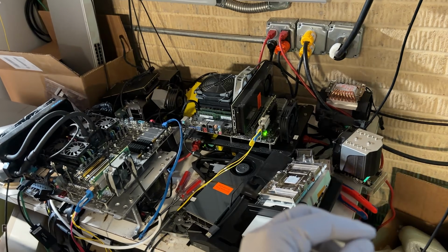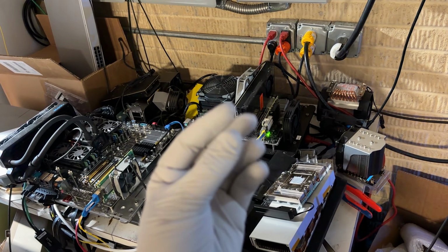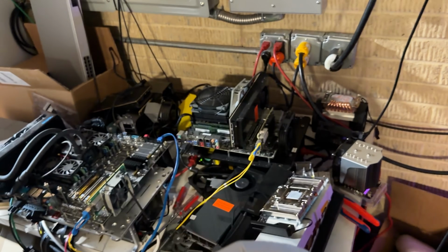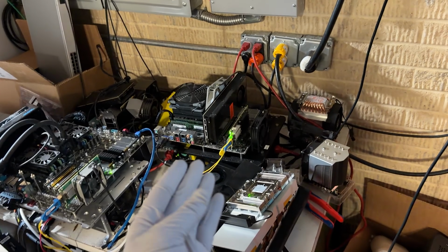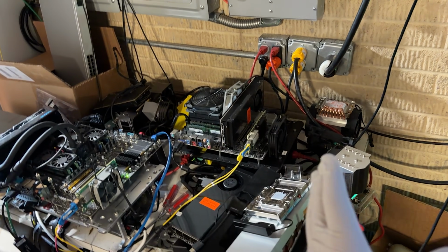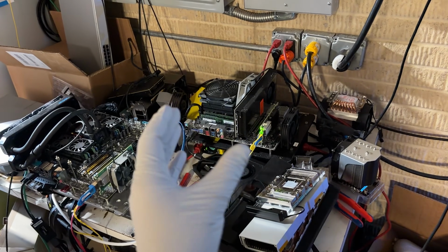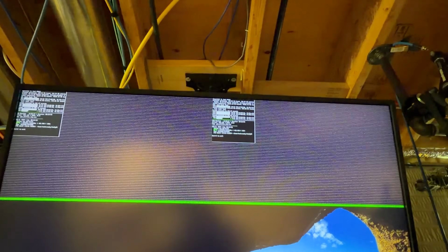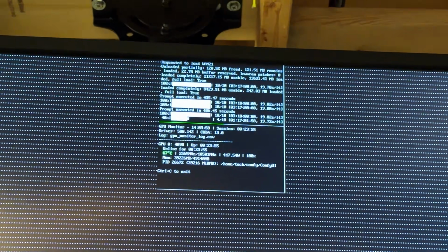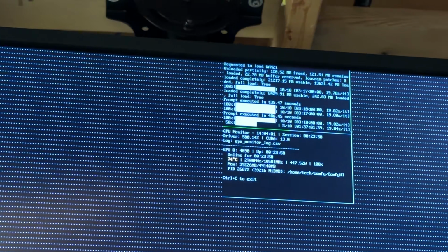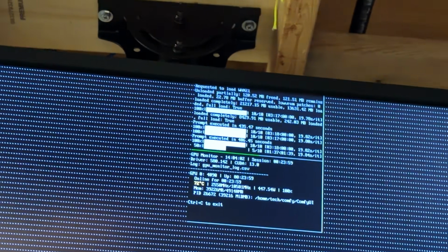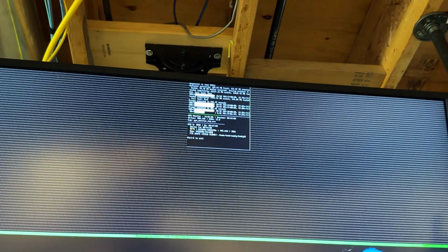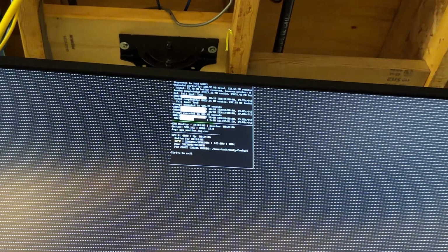This is more than likely what it was with a solder ball issue, because the memory modules themselves had lead-free solder under them. So I put on all the memory modules onto a new PCB with a completely new core from another donor card, and the card works now, and it's running the comfyUI workload. I'd say an interesting fault I've not seen before, where a cracked solder ball or a bad BGA connection because of the solder was on one of the chip select pins. So I think that's what caused the issue with going over 24 gigabytes.